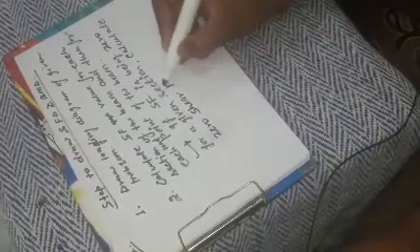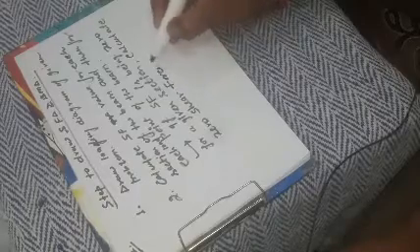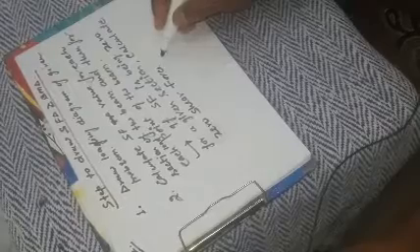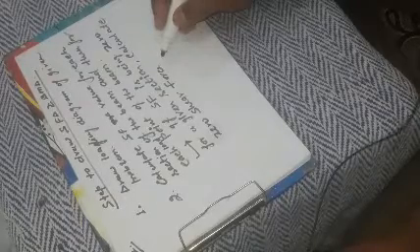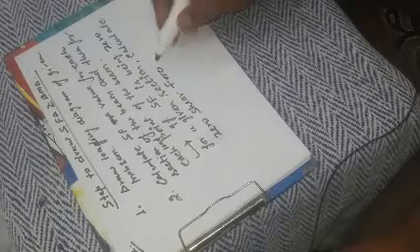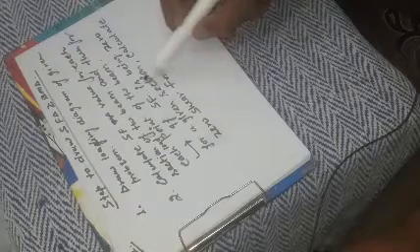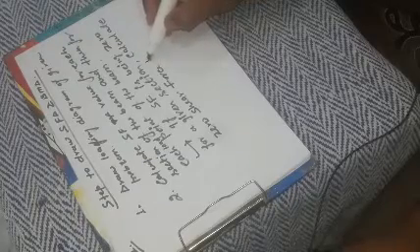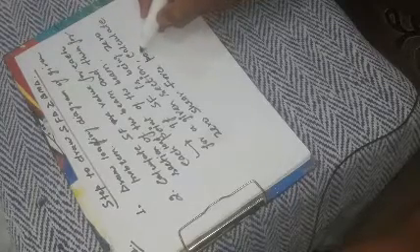Why? Because further in derivation we will show you that in a given section at zero shear force point, bending moment is always maximum. So it is required, if in a given section shear force is being 0, then calculate zero shear force point for that section.